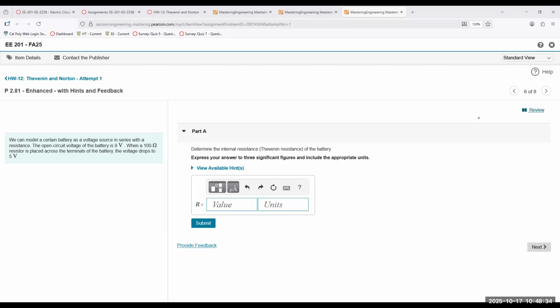Once you make that connection at the beginning, you don't need to disconnect it until all three measurements are done. Don't do anything to this. You just take your meter, you connect it to your circuit A and B. Then what you're going to do next is you put it in current measurement mode. So you measure first IN, next you measure VTH, and third and last, you measure RTH. And there's a reason for this.